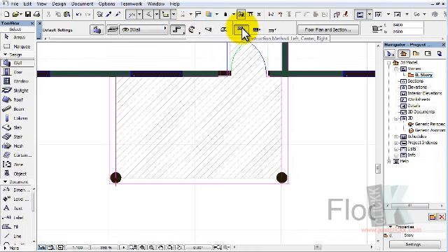And how do you want the walls to lap? Is it center to center or in to in? So I'm selecting this in to in option. Since it's a suspended wall, how do you want to suspend it? What's the elevation? We are giving it 2500 as the base. That's the offset for the suspension, and it will vanish at the same height as the building.